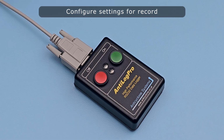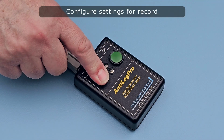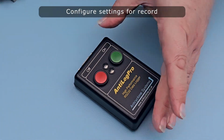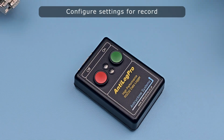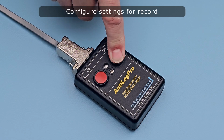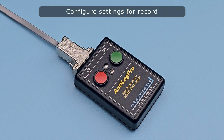Now power down the data logger. Remove the null modem cable. Connect up the GPS signal source. Power on, and you are now logging GPS sentences.